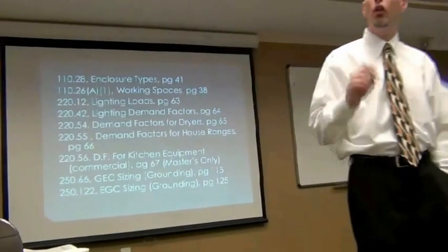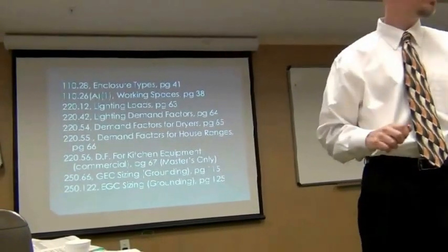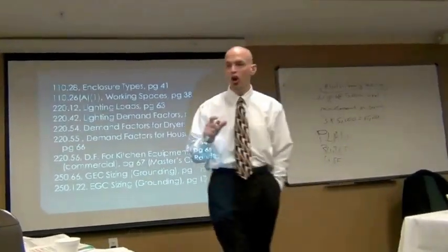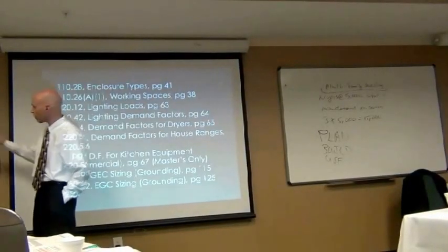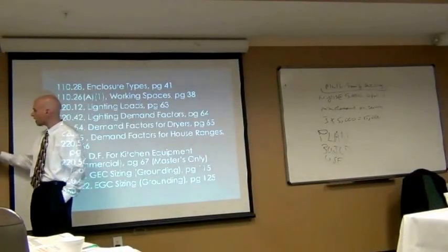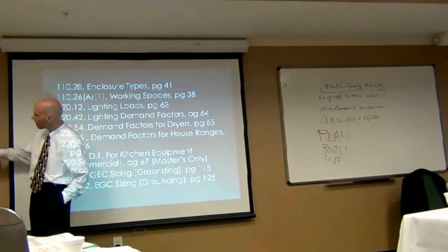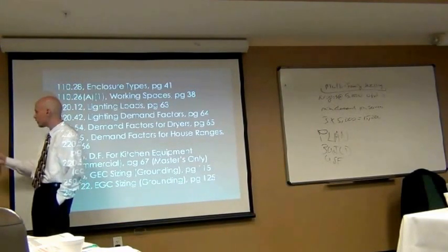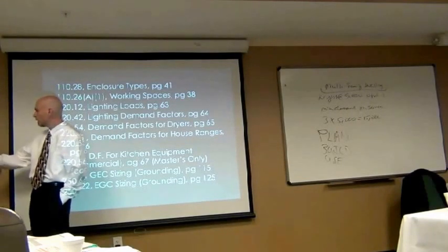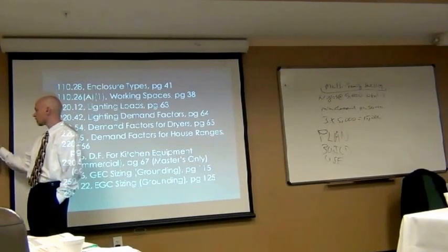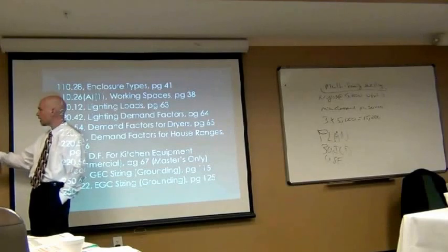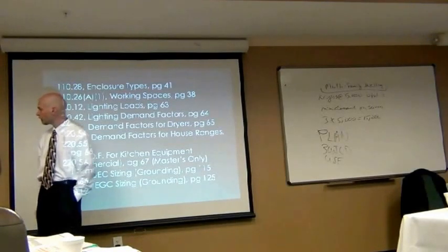Okay. If you look right below the table under note 1, that tells you that we're going to take the sum of all the ungrounded conductors in one set. So I've got 5 conduits here. Within each conduit, I've got 1, 2, 3 250s, and I've got my GEC, which we're trying to determine the size. Sometimes you may have a 4th one if it's a 3-phase with a neutral side service. So you'd have 4 wires there, and the 5th one's the GEC.